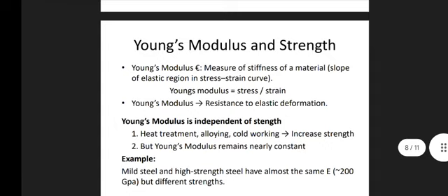Young's modulus and strength. Young's modulus is the slope of the stress-strain curve in the elastic region, the resistance to elastic deformation. Young's modulus is independent of the strength.